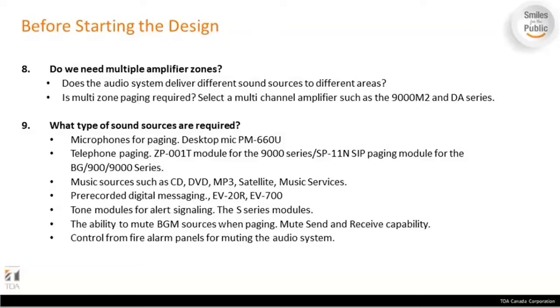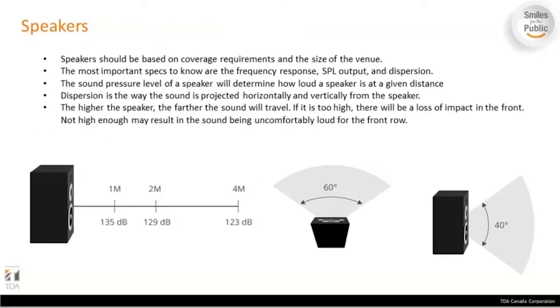So basically, just to make it simple, we need to understand what the client needs first. Second, derive what kind of speakers, what kind of zones, and what kind of amplification, and whether or not they need processing. Do they need emergency announcements? Do they need background music? And get insight into what the client will need firsthand. Now, coming to the next interesting topic would be speakers. So based on your coverage, what area you want to cover.